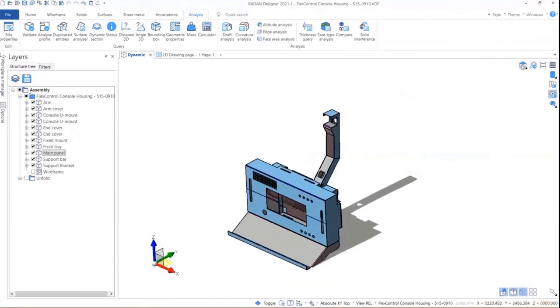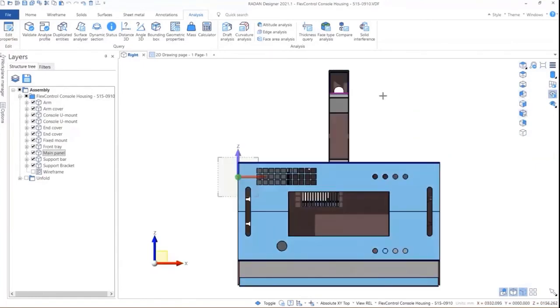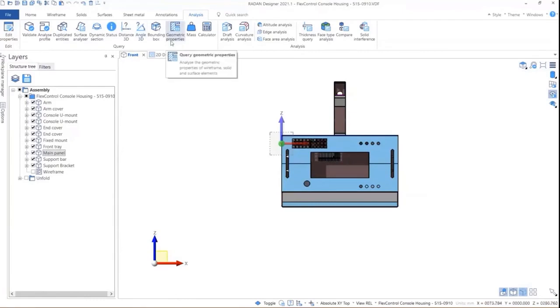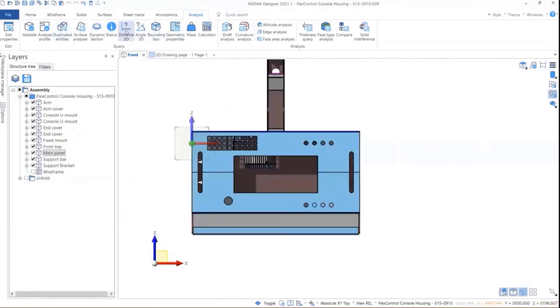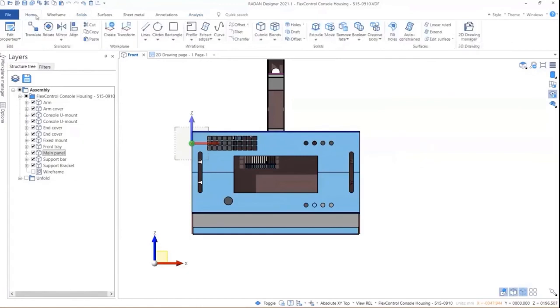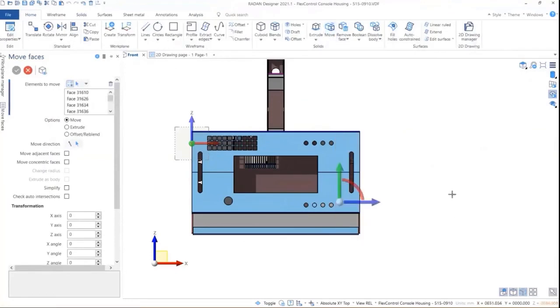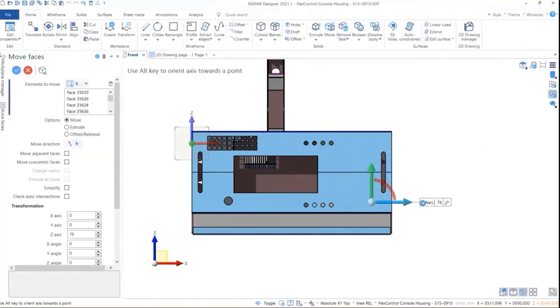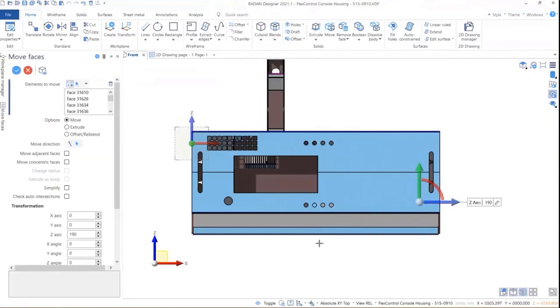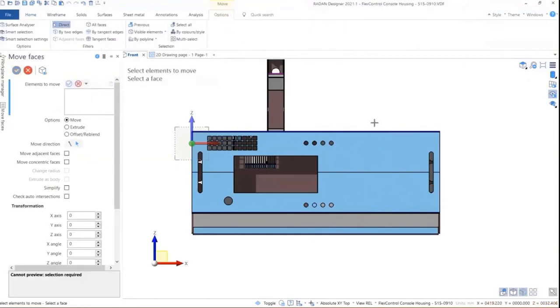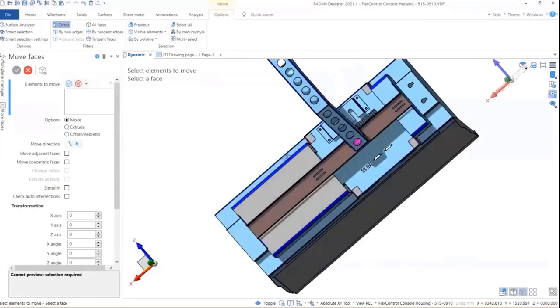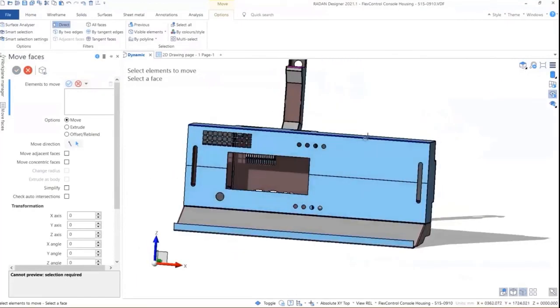And in fact, let's do a stretch on here. So let's come in here. So we're looking at that, and this is again, I think, one of the real powerful features of Designer, that I've got a sheet metal assembly there, and what I want to do is actually move or stretch the whole assembly, and all I need to do is do something like that, and then I can simply drag those parts. So I've stretched all of the parts that were included in my window,